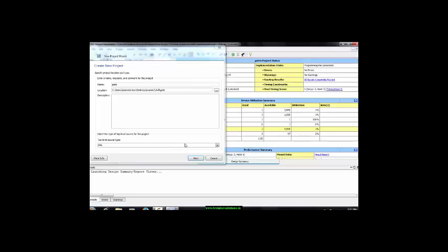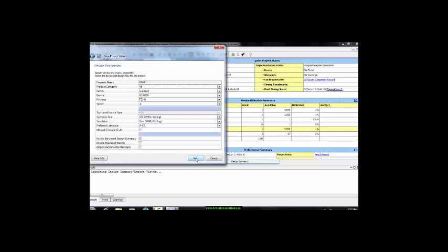Okay, the top level source type is HDL, it's fine. Press next. Okay, these are the device properties, that is, what type of chip we are using. So we are using the Spartan 3 family. Device is XC3S200. Package is TQ144, with 144 pins. Speed is specific for this chip. The synthesis and simulator tool will be in VHDL. It can be Verilog also. Preferred language is VHDL. Okay, everything is fine. Press next.